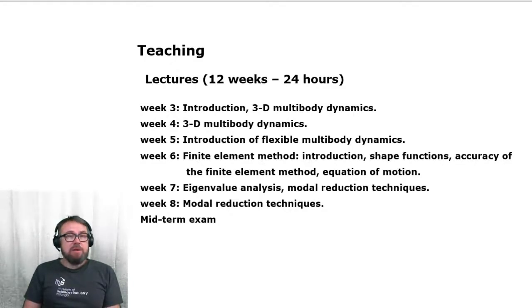And then we're going to move on to another space. If the finite element method is all about describing the nodal positions and nodal displacements, then we're going to move on to another space, which is modal. So we're moving from nodal to modal space. And in that, we're going to take a look a little bit at eigenvalue analysis.